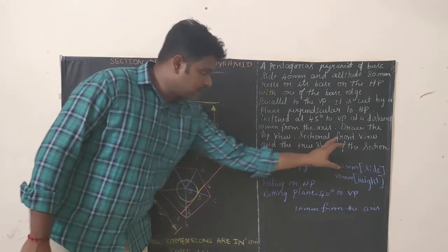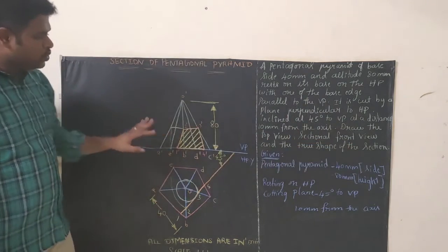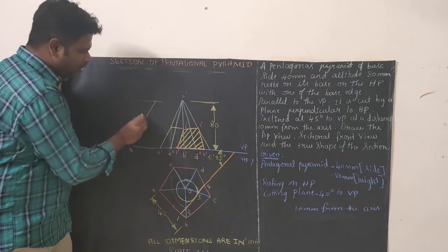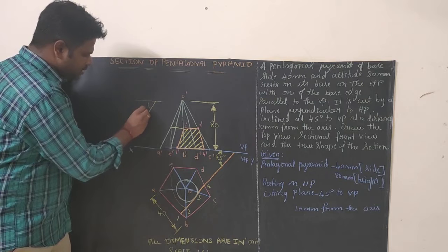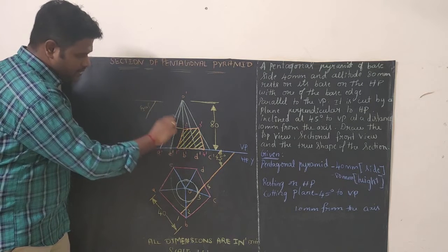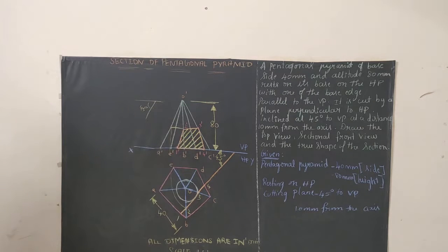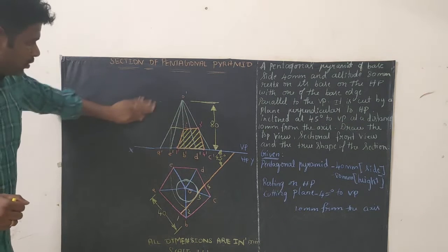That's what you ask. Sectional front view. After that, you do hatching. Hatching is just draw a baseline and take 45 degree, keeping this line as a reference. This is 45 degree, keeping this line as reference. Try to hatch in such a way that the hatching should be done at 45 degree angle and equal spacing, and later on you try to rub it off.